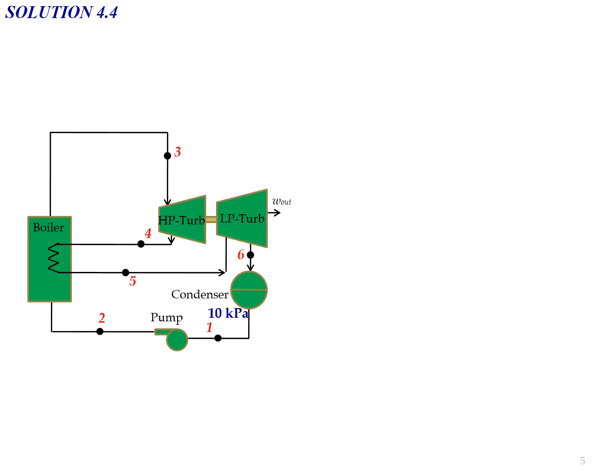According to the data given in the question, because we consider the ideal reheat Rankine cycle, we will have a constant pressure heat rejection process at the condenser. So P1 will be equal to 10 kilopascal and P6 also equal to 10 kilopascal, and we have 15 megapascal for P2. During the heat addition process for the ideal reheat Rankine cycle, the pressure is constant. So P3 also will be equal to 15 megapascal.